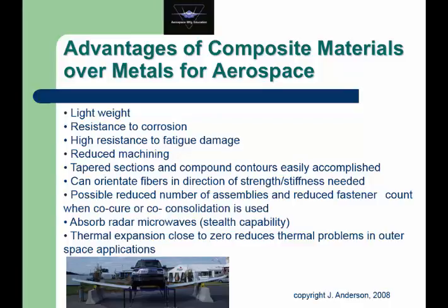It's possible to reduce the number of assemblies and reduce fastener count when we co-cure, that is, take two fiberglass or two composite parts, and we cure them together, or co-consolidation is used. And we'll see a slide, a couple of slides down, that talks about a study that was done on the L1011.